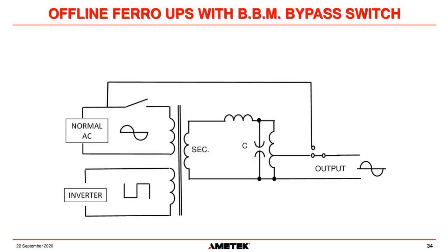The downside was if you had a very unstable power source, they would be constantly switching back and forth between batteries. So that was a potential problem. The manufacturer liked to call this an online UPS, and the industry didn't quite agree. The guys that made these things were really good at marketing, so they claimed they had a static switch here because of the switch on the primary up there, but that's not what a static switch really does. The downside of this type of design, because there is no actual static switch in here, is that a capacitor failure on the secondary of the transformer takes the output voltage to zero, and you lose the load then, and there's no way to recover from that.